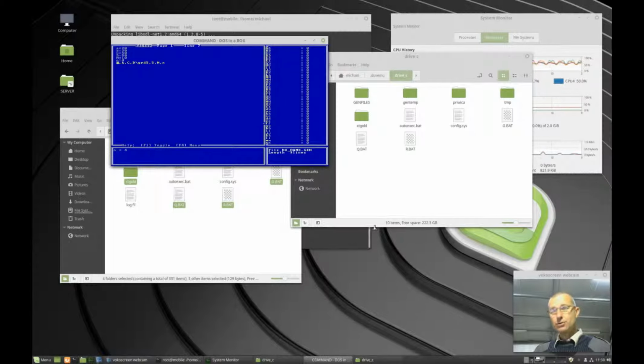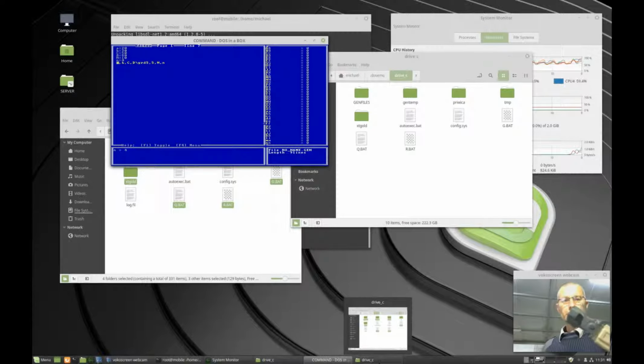So what I've had to do, just grab the thing. This is a device designed to give you a USB port to RS-232. Now I'll just show you what that looks like. So that's an RS-232 socket, and that's provided by plugging that into the end of this, which is a USB cable connected to the computer, and then the RS-232 connection goes into this device. So it emulates RS-232 from a USB port.